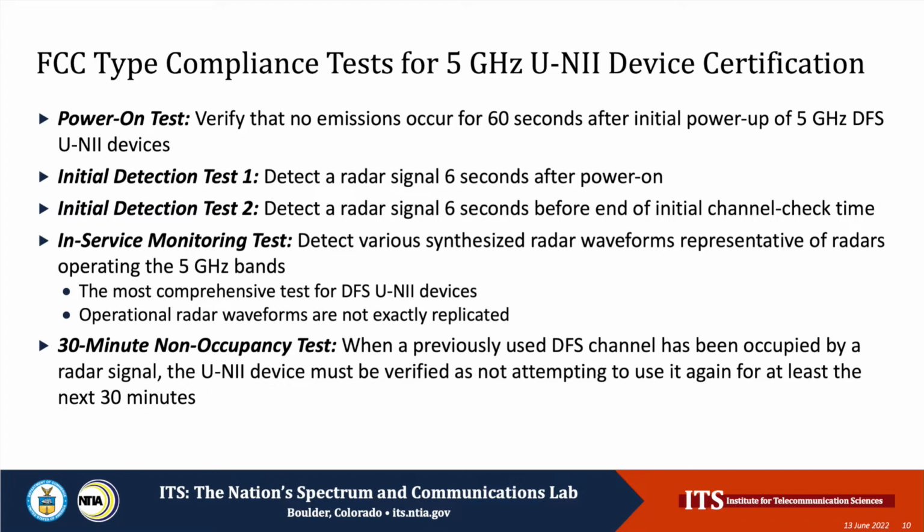Then, when a device is running in its normal mode, various synthesized radar waveforms have to be detected in the 5 gigahertz bands in what's called in-service monitoring. This involves the most comprehensive testing for DFS UNII devices, and it does not precisely replicate, this is worth noting, any particular exact operational radar waveforms.